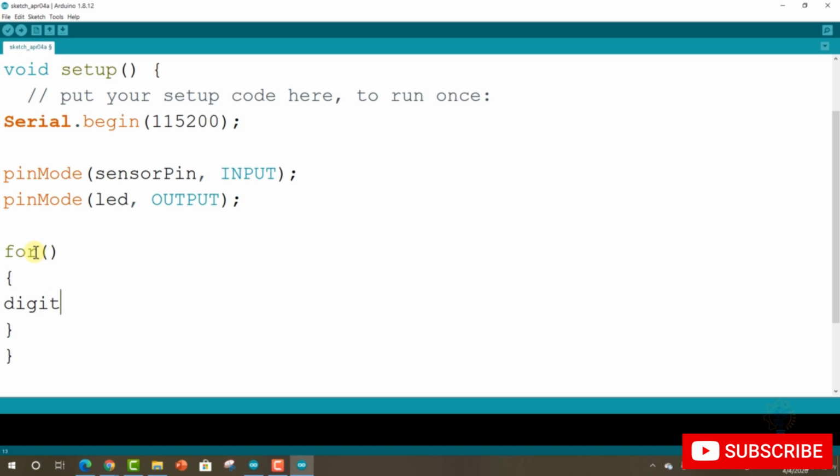We need to use digital write to turn the LED on, or high. Then we need to use the delay method. As you can see, delay. This delay method will blink for a certain amount of time.